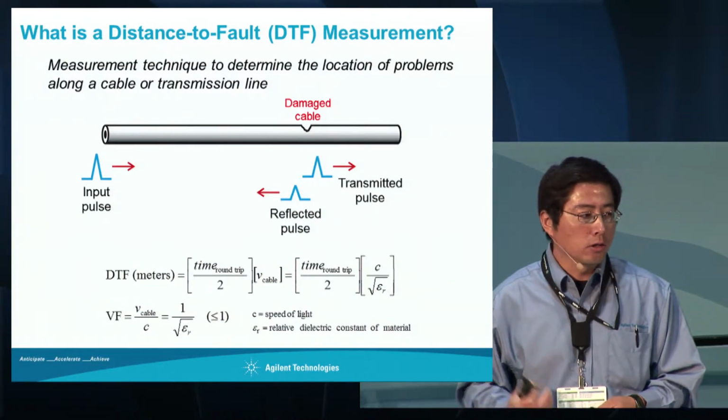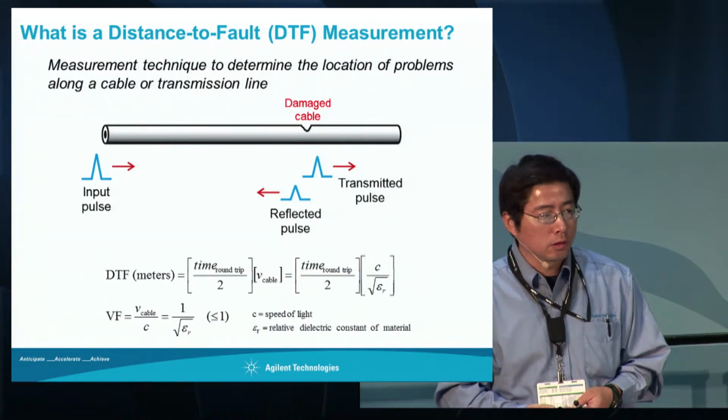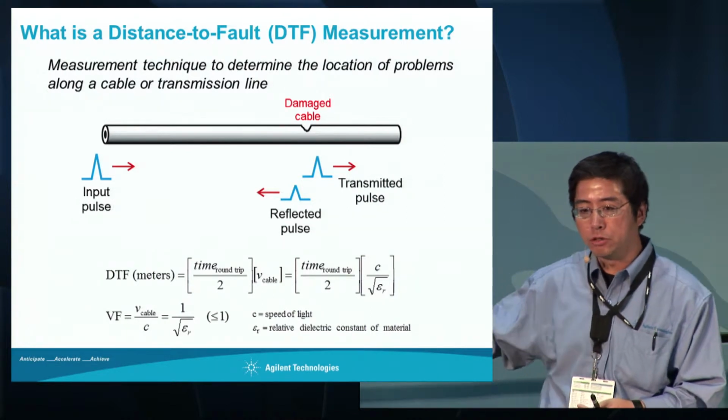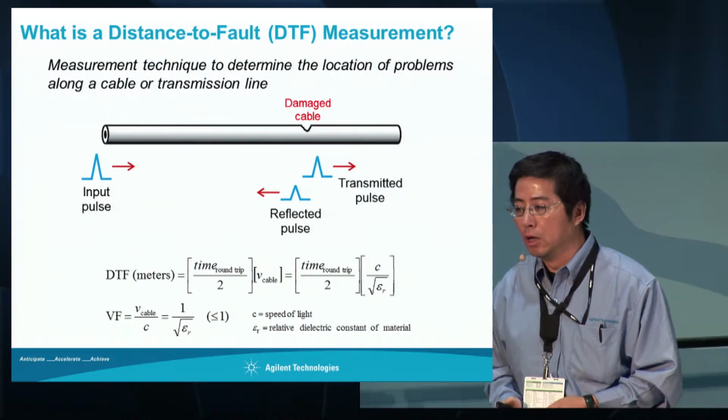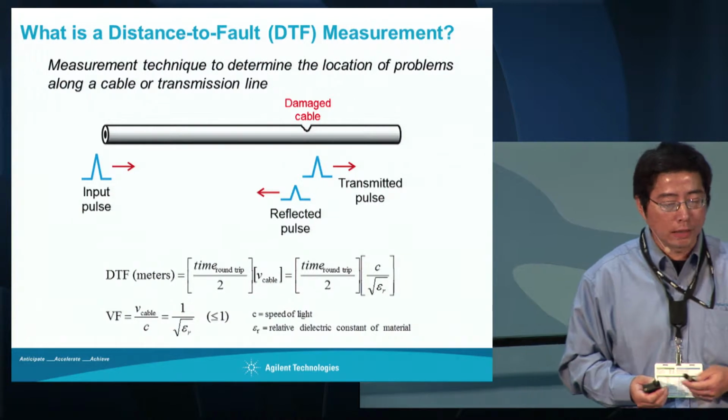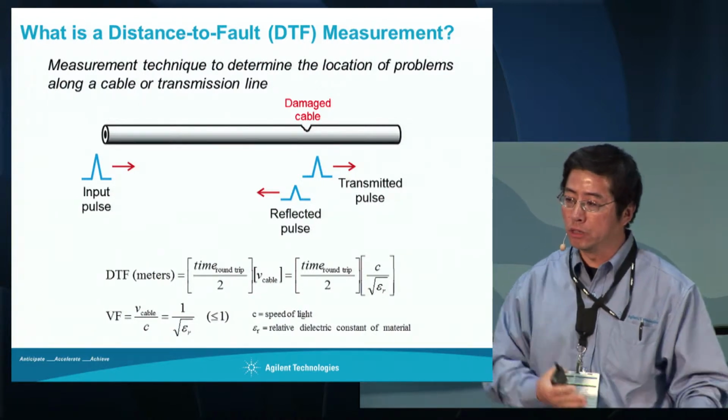The technology we use here is different from the TDR used in the old days. With TDR you send an impulse signal, so if you have any impedance change, you see a reflected signal. What we do here is called FDR, frequency domain reflectometry. Essentially we take the return loss and do an inverse FFT to convert it into time domain. It's easier to do and more sensitive, because sometimes a slight impedance change TDR won't be able to detect, but in the frequency domain it's a lot more sensitive because we detect the phase as well.